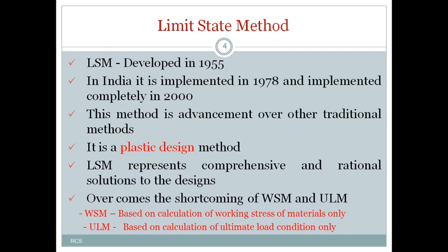That means the structures designed in the working stress method are based on elastic theory, so they will not go beyond the elastic limit. And if we consider the ultimate load method, we are designing the elements based on the ultimate load. That means that falls in the ultimate region of the stress-strain curve.